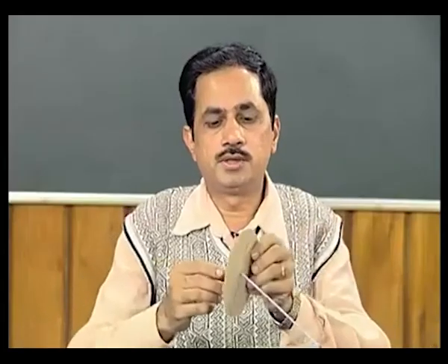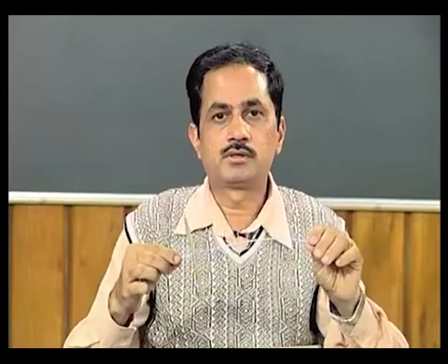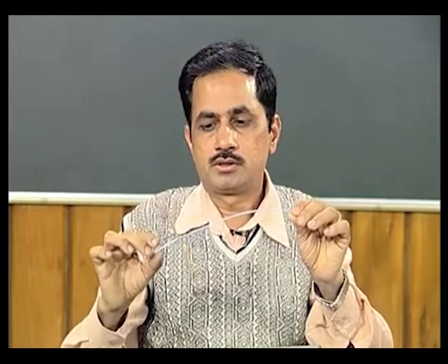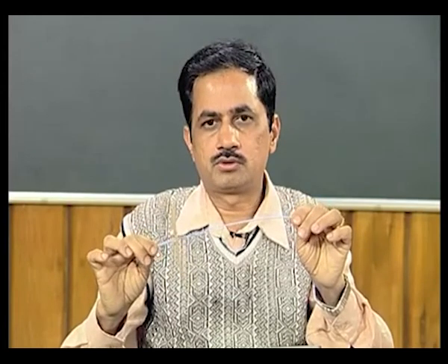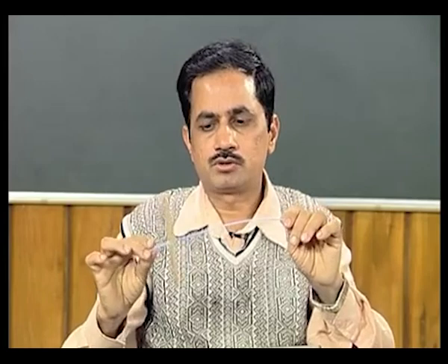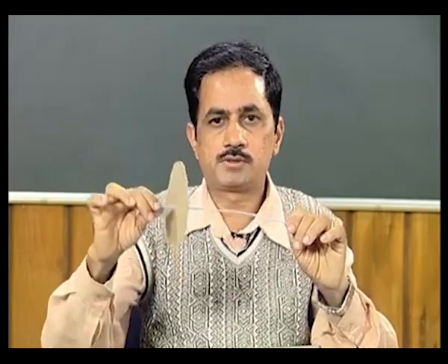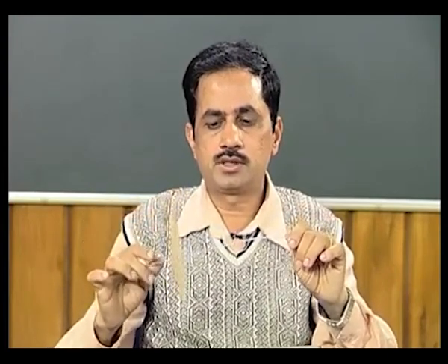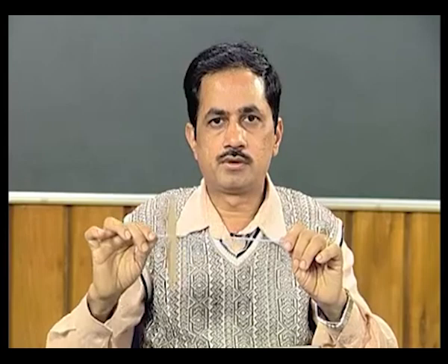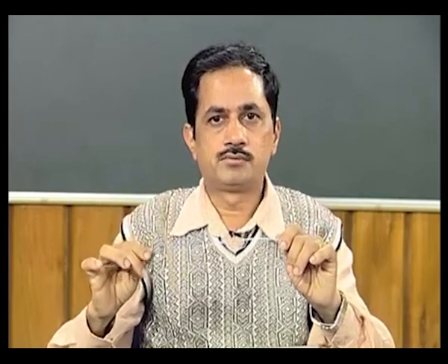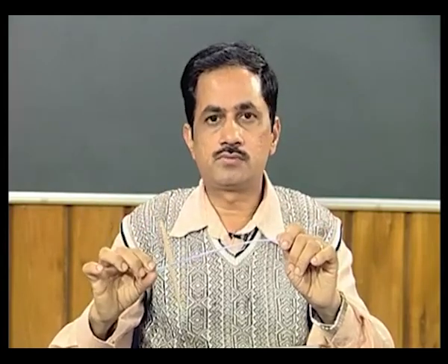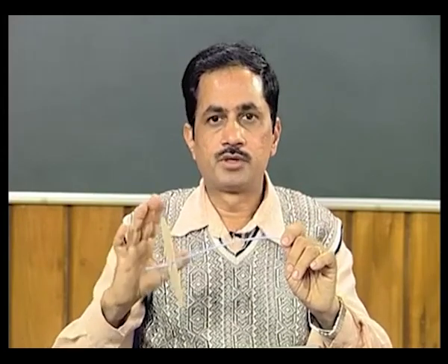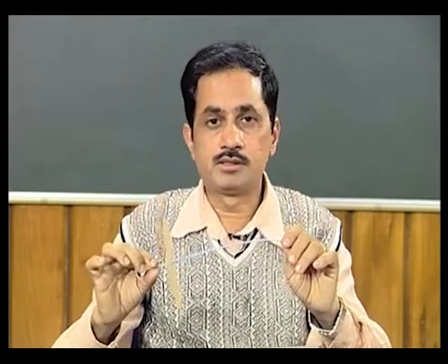For the present case we will be considering a cantilever beam like this, and this shaft will not only be spinning about its own axis, it will also be whirling. So spinning and whirling both will take place, and we will consider the spin and whirl frequencies different, and try to see how the whirl frequency changes with the speed. Again, we will not consider any unbalance in the rotor.